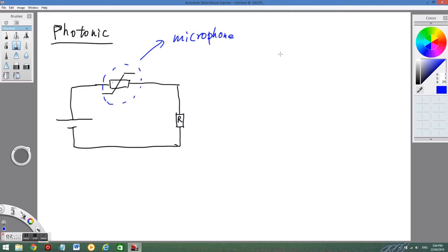So when I talk to you, when the sound is traveling in the air, the sound actually pushes the air forwards and backwards. Okay? So the way they turn a microphone into a variable resistance is they do something like this. Imagine if I have a wire on both sides, they put some material in the middle. What's happening is this material in the middle, as I talk to the microphone, sometimes goes down, vibrates.